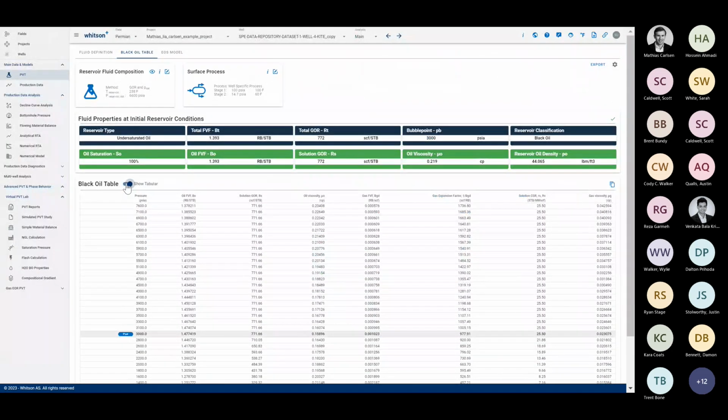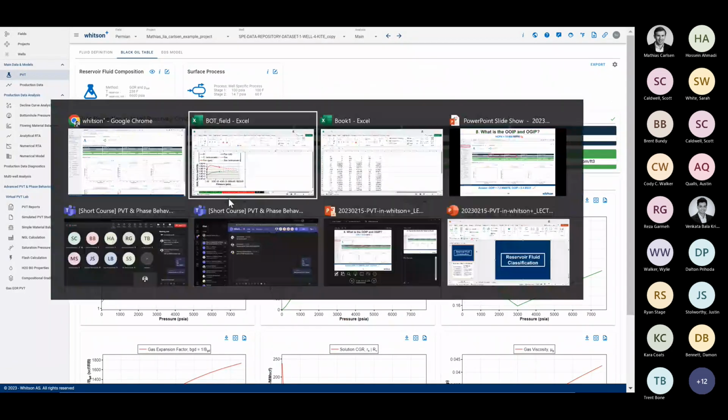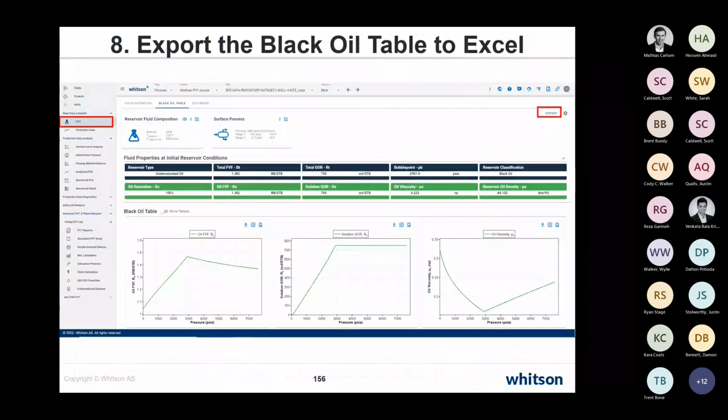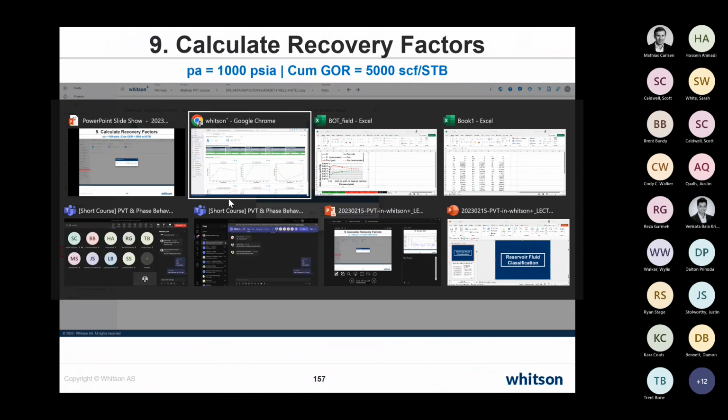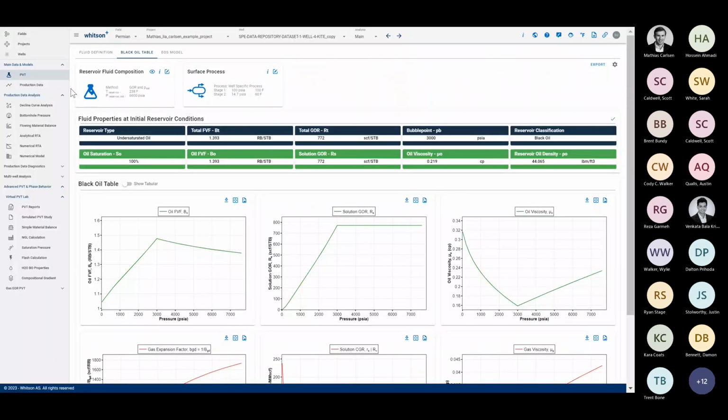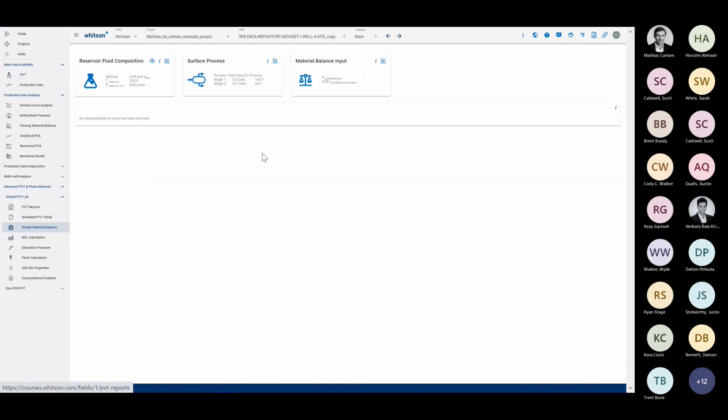Very good. The last thing I wanted to show with regards to this, before I go in and run, okay, let's do one last thing, just a simple material balance calculation. Again, if you have an estimate of what your abandonment pressure is and your total GOR at the end of history, and you have the fluid initial conditions, you have what's required to calculate a simple material balance.